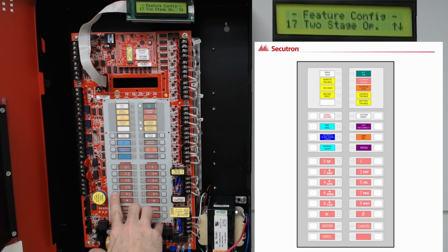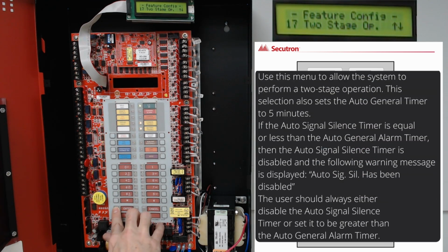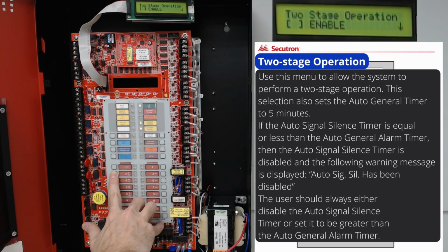The next option for Feature Config is Two-Stage Operation. By pressing Enter, we get to enter into the options for two-stage. If we'd like to have the system act as a two-stage system, we'll hit the up cursor and enable the two-stage by applying the X using the left or right cursor arrows and selecting Enter and then Cancel to exit back out to the previous menu options.